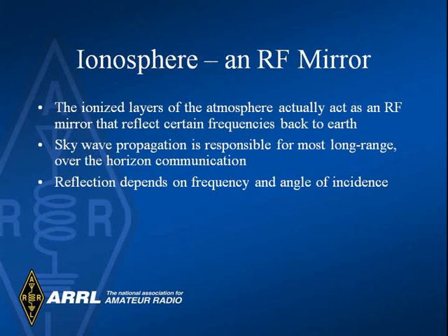The ionosphere is composed of several ionized layers that act as an RF mirror to reflect certain frequencies back to Earth. Skywave propagation is responsible for most long-range over-the-horizon communication. Reflection depends on frequency and angle of incidence.